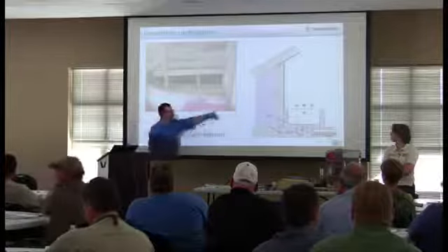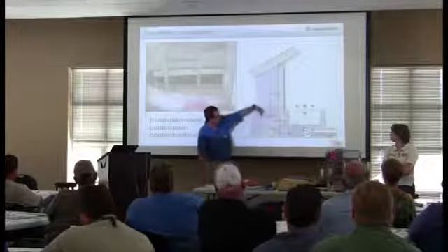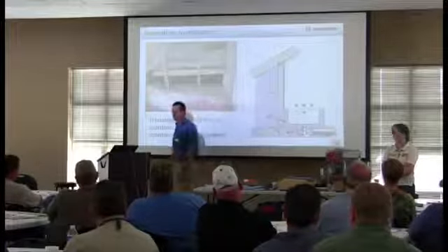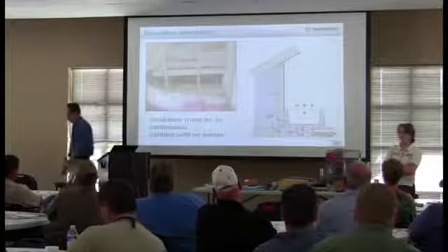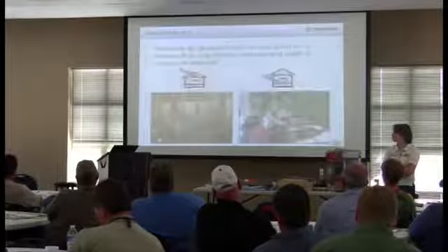So the pathway for this is a common sort of flaw or hole in your envelope, where air can leak right through the insulation, or in this case, there was no blocking under the knee wall. And those are both, explicitly, the energy code says you can't do that. So big comfort problems as well.